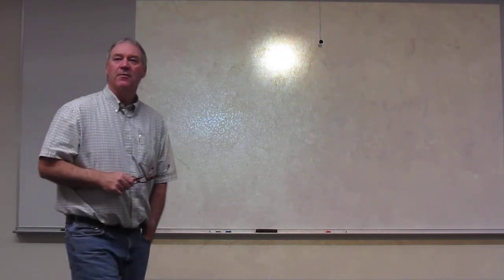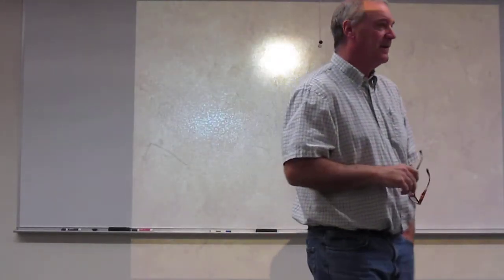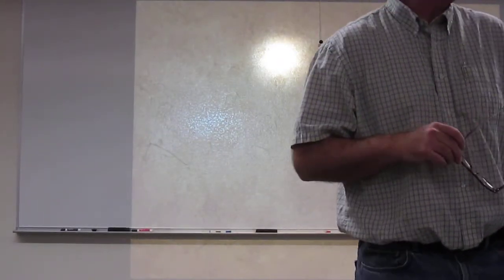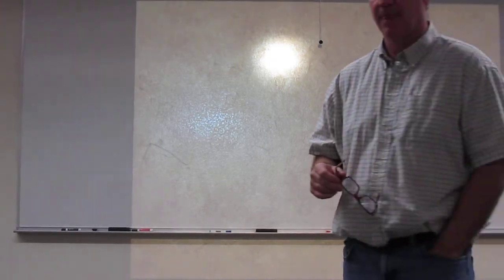Now, nominal, we got a bunch of definitions, and these kind of pop up starting on page 845, and let's go ahead and look at those. So what does nominal mean? You can read it right out of the text on page 845. A dimension used to describe the general size, usually expressed in common fractions. Folks, a nominal size will be dictated by your workforce. And it's usually done fractionally, even if we're using decimal dimensioning.